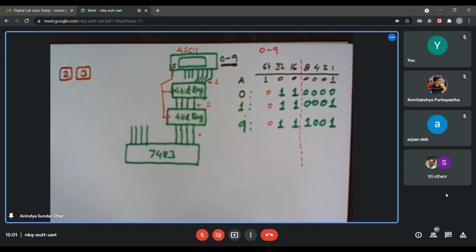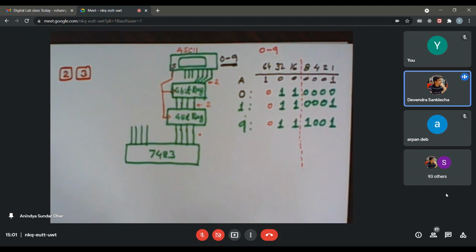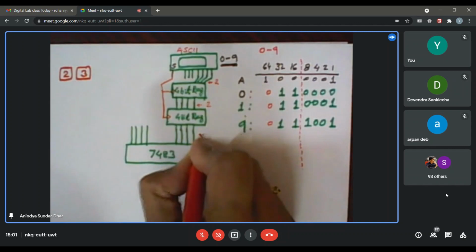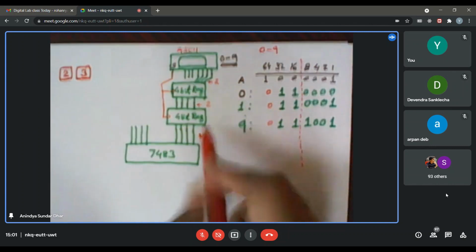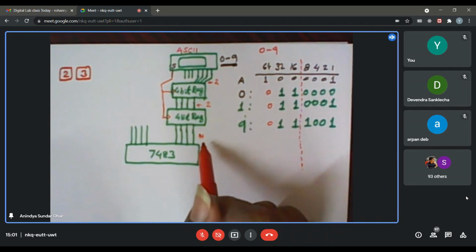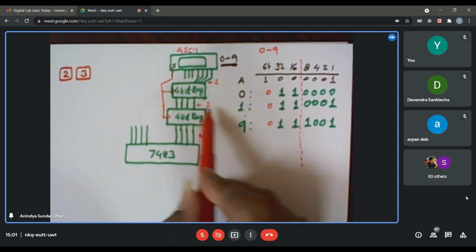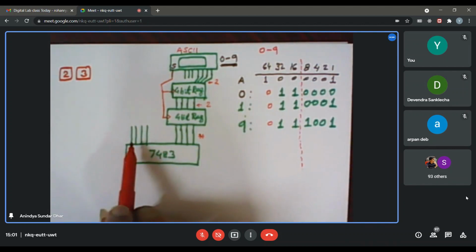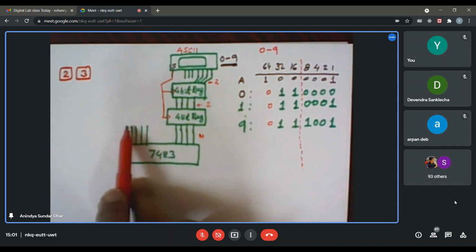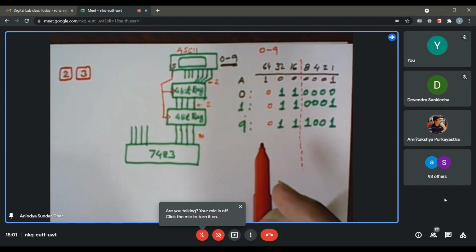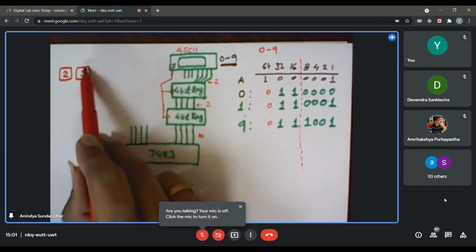Any idea? Some garbage value. It could be a garbage value. We cannot rely on it, or say that it will be 0. Maybe in a simulator it will become 0. Simulator assumes an ideal environment, but in lab, whenever you switch on the power, there might be some noise. So there could be a garbage value. Now where am I supposed to connect the other side of these 4 inputs? The output of the first register, because as soon as I press 3, what will happen?